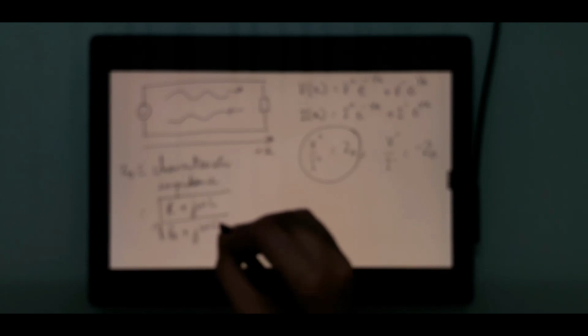We know that Z0 is nothing but the characteristic impedance. And we had defined it in this format, where R, L, G, C are per unit length quantities of the line. So if you keep omega constant, the fact that R, L, G and C correspond to some kind of impedance shows that this impedance depends on some of the characteristic properties of the line, that is the R, L, G, C. Hence Z0 is called the characteristic impedance.